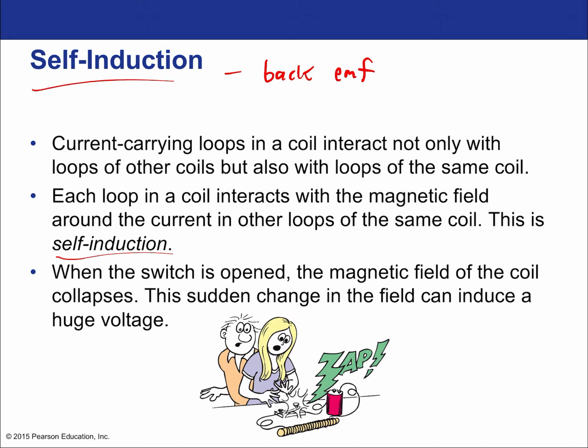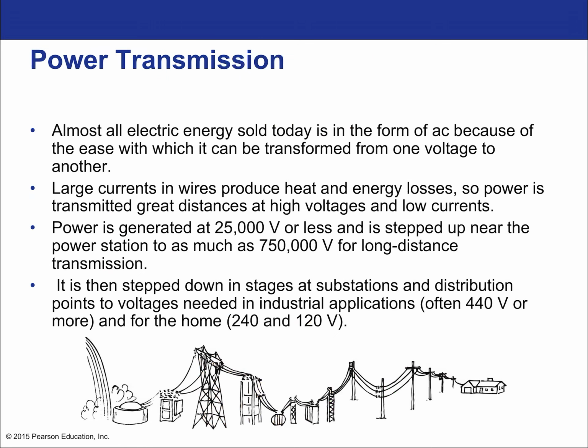That's why motors will overheat if they stop moving, because now there's too much current flowing through the system based on its specifications, and it can't handle the actual output of energy due to that much higher current, because the back current isn't there anymore, and so you've got a big number without the subtraction, okay?